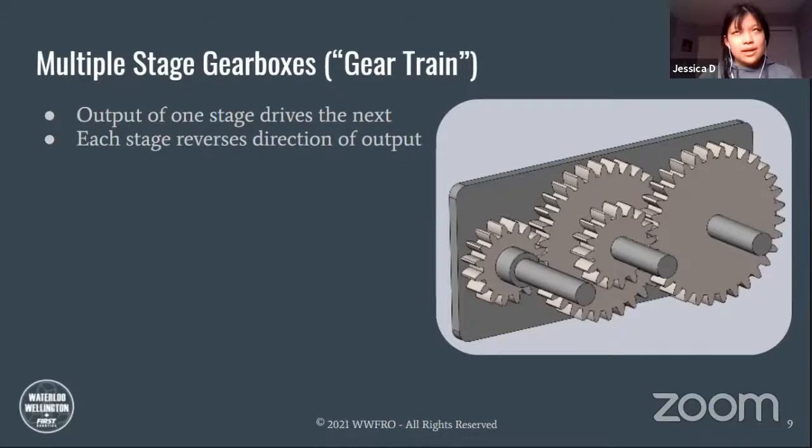That goes back to what I said about clockwise and counterclockwise with spur gears. So maybe you can follow through with me, but let's say we're turning that first gear clockwise. The second gear meshed with it is going to turn counterclockwise. And because that third gear is on the same shaft as the second one, they're going to turn the same direction, so also counterclockwise. And then when the third one meshes with the fourth one, the fourth gear is going to move clockwise again. So basically, you can think of these two gears as the same direction since they're on the same shaft. So it's clockwise, counterclockwise, and then clockwise again for each of those shafts.